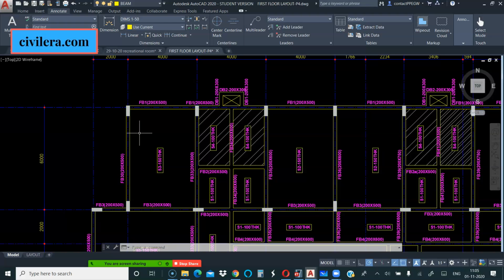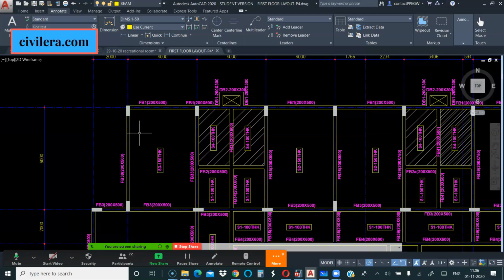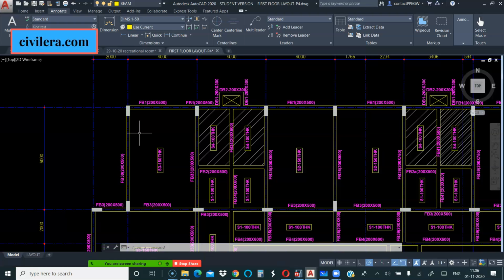It's not true. But if you place columns at say 3 meter intervals everywhere and then get say minimum steel of 0.8% for all columns, then yes, you are wasting money, because simply for the reason you are giving a minimum steel, you are having more number of footings and things like that.